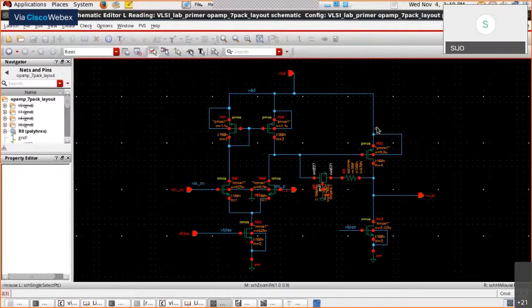So we have looked at the circuit perspective. Also, we have looked into the frequency compensation part of it. We chose the compensation capacitor and also the RZ value as a nulling zero resistance. For that, we have done a layout, so we'll quickly look into how the floor planning can be done in the available time.